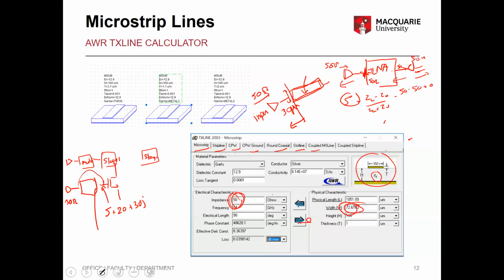What you need to have is something called conjugate matching. The impedance that you see at this point, this is not the reflection, that's the impedance, should be Z1 star. If you can somehow present 20 minus 30j, the imaginary parts cancel out. So it sees the real impedance 20 versus the real impedance 20, and that allows the power to transfer with minimum reflection.